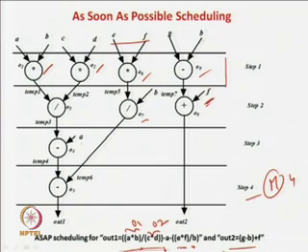Similarly, for this addition operation, you know that G plus B and G minus B are already scheduled in time step 1, and O9, that is this addition operation plus F, can now be scheduled in time step 2 because O9 depends on O8, and O8 is already scheduled in time step 1. So, you add 1 to time step 1, you get time step 2. So, O9 is scheduled over here. So, actually we are pushing everything as early as possible. So, now this thing is done.